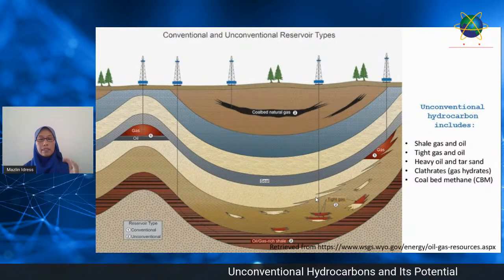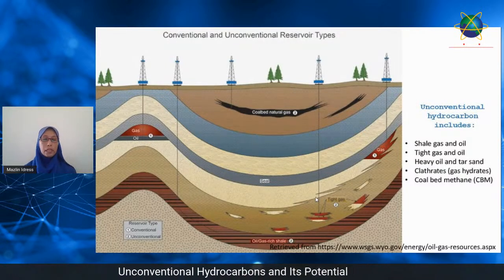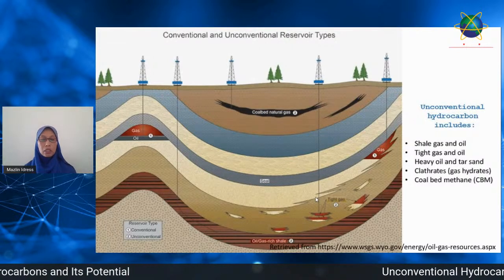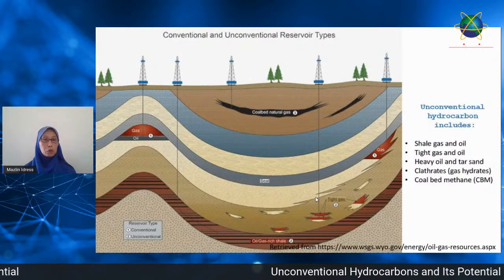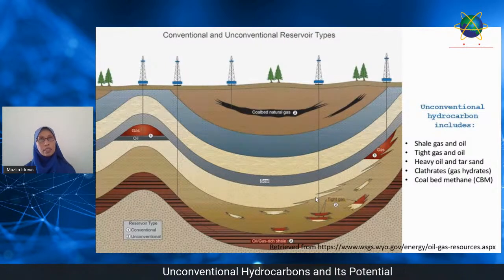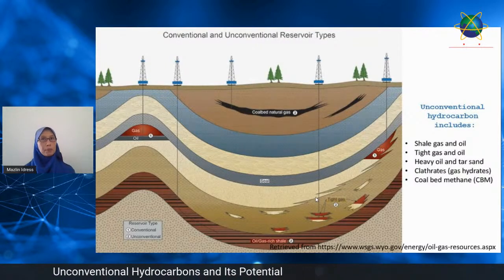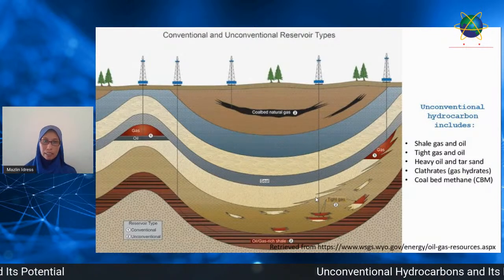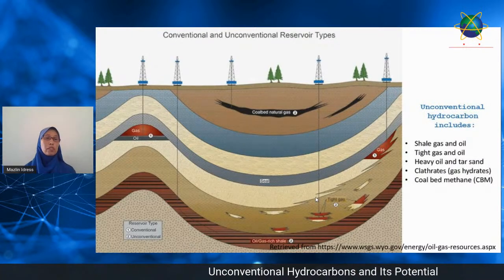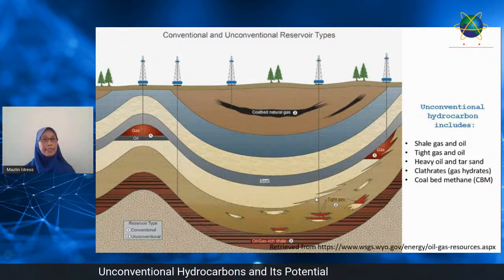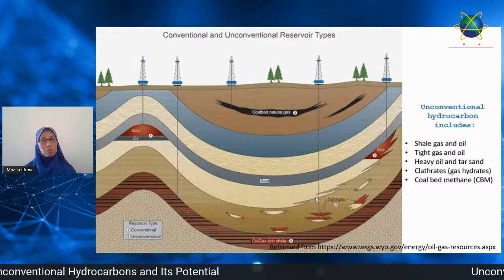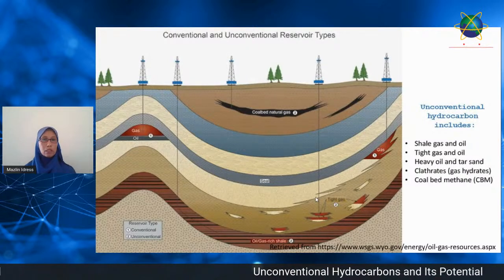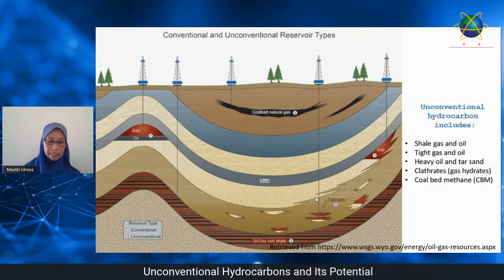For coal bed methane, they drill in, putting in a steel cased hole. It is drilled into an underground coal seam, and they pump out the produced water through tubing. So it's reducing the hydrostatic pressure inside the coal seam. When the hydrostatic pressure decreases, the methane gas can escape from the coal seam, dissolve, and go up to the surface.